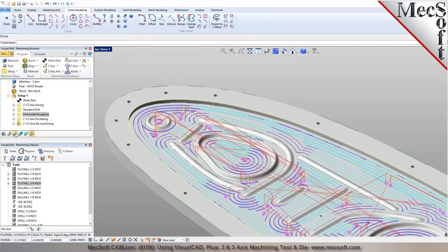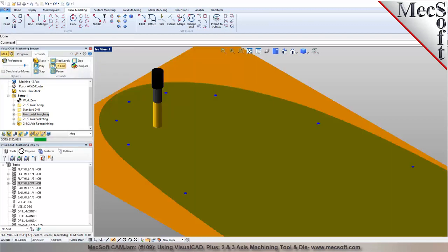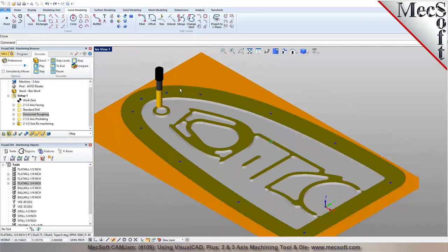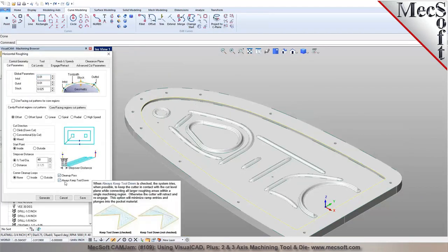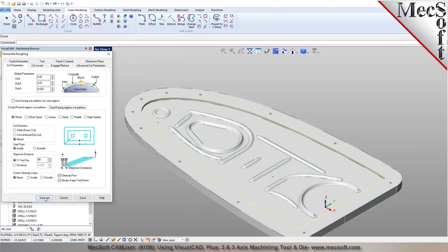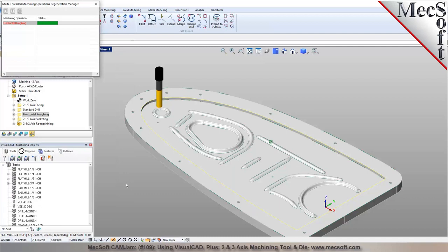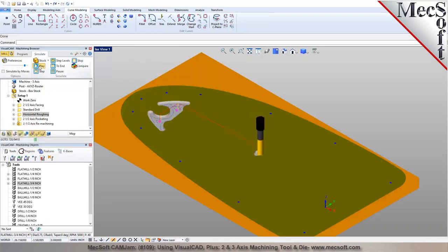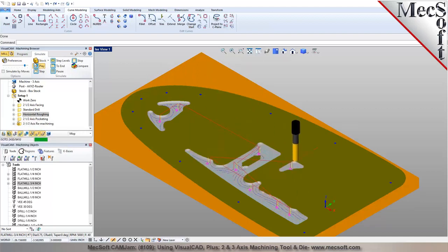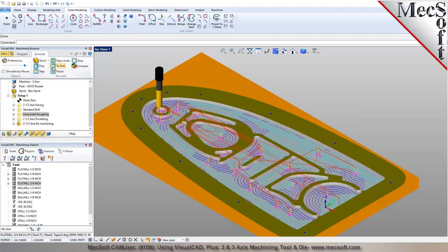So now on finishing, can I tell the tool to remain down? Yeah, so in the roughing operations, we have the option to do a cleanup pass and always keep the cutter down. It'll do the best possible not to retract the cutter when you go from one area to the other. If it's possible to find a route, when areas get pinched out, it'll try to keep the cutter within the same area and avoid the retracts wherever it's feasible. If it has to retract, it'll do the minimum retract and then ramp back in, as you're seeing.